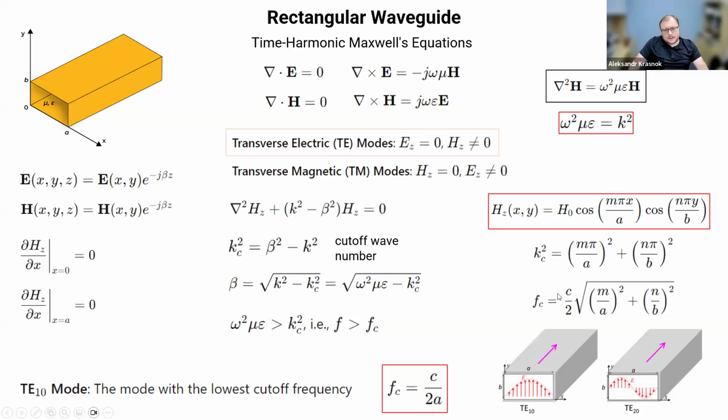So it's defined by this formula here, the cutoff frequency depending on the mode order and the size dimension of the waveguide. Below this fundamental mode, you won't have any modes propagating, right? No modes propagating below this frequency. Just above this frequency, but before the second mode, which will be TE, I believe, 1, there will be only one waveguiding mode.